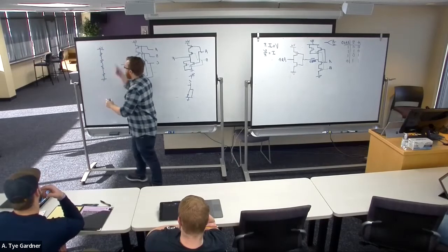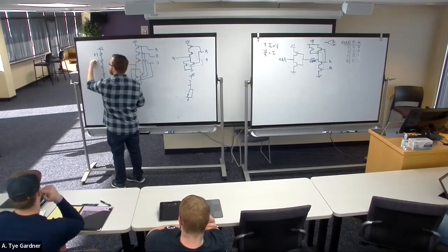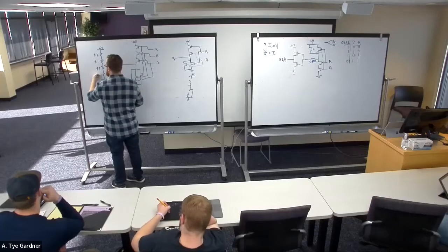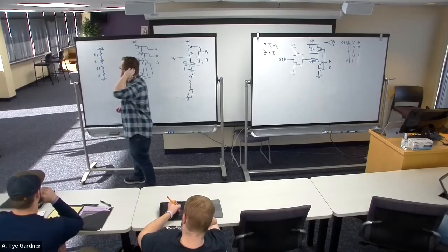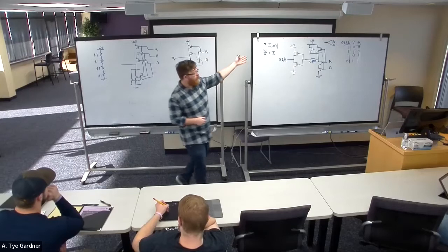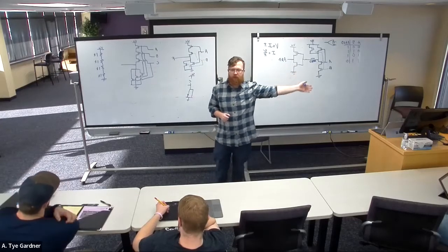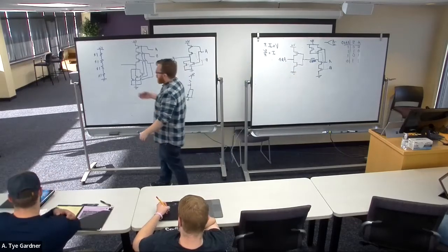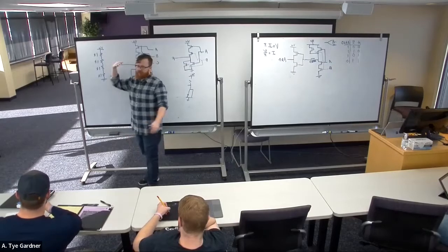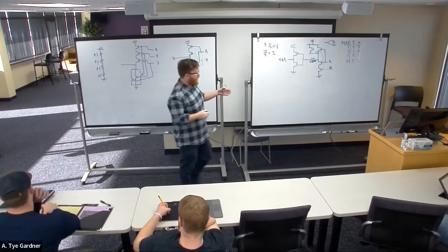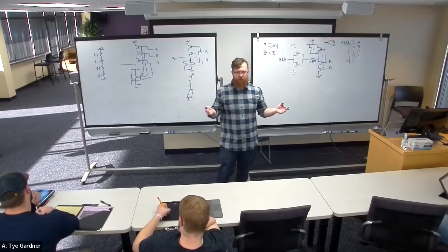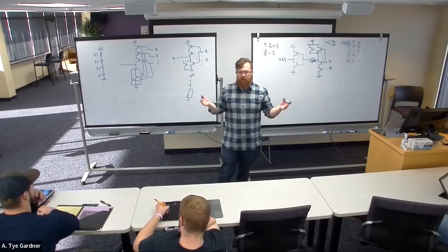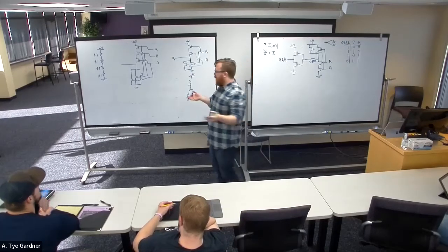So let's say this is 5 volts and each of these are 1K. And now I have this relationship, so I have Ohm's law, right? And the resistance, each one I throw in series is adding up, but we've already kind of established that no current ever flows through these things, hopefully. So the current's not really the issue, except for the leakage.